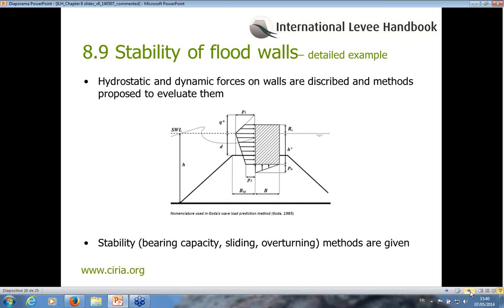The section reviews the methods of justification regarding bearing resistance, sliding, overturning, overall stability, structural failure, etc. The main principles for the evaluation of the stability of I-walls are also discussed in terms of hydrostatic and hydrodynamic loads, earth loads, seepage effects, etc. The effect of cracking is discussed as regards the Katrina experience, and a brief discussion on advanced soil structure interaction and finite element methods is proposed.